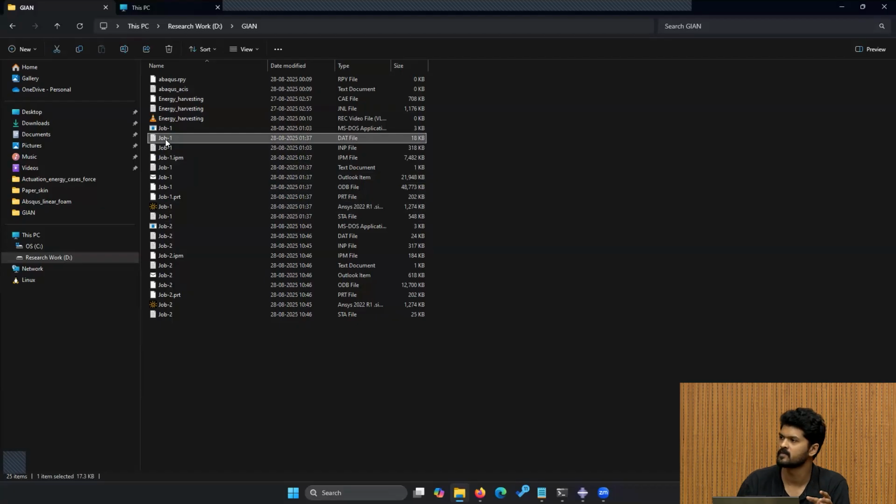It will contain your mesh information, geometry information, contact information, interface information, boundary conditions, loading conditions, everything. Plus, how your system is handling your job: the amount of RAM it is taking, the clock time it is taking to solve the problem. But the file that will be submitted to your solver is the input file. It has the extension .inp.